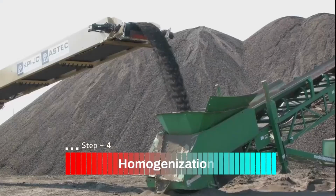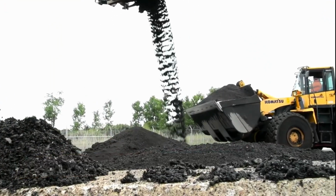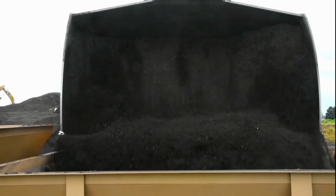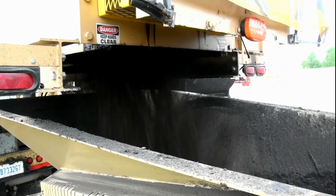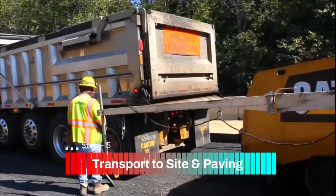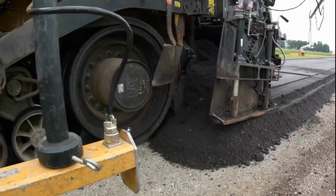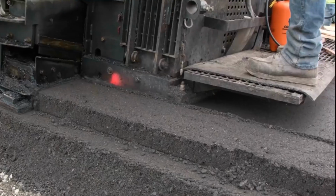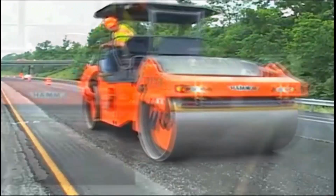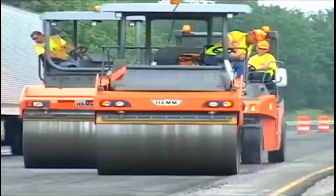Step 4. Homogenization and storage. The mixture is blended in batch mixers or drum mixers to ensure uniform consistency. The processed material is stored briefly before transportation. Step 5. Transport back to site and paving. The processed material is loaded onto trucks and delivered back to the roadside. A paver spreads the material evenly across the road. Compaction is done using rollers to achieve the desired density.